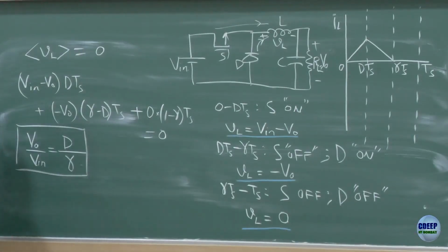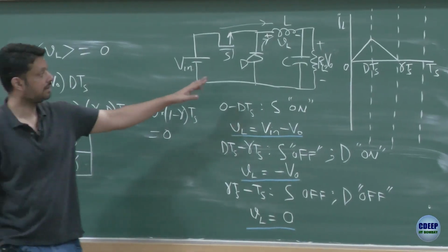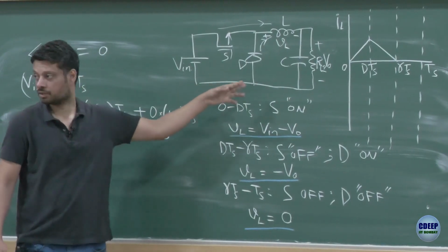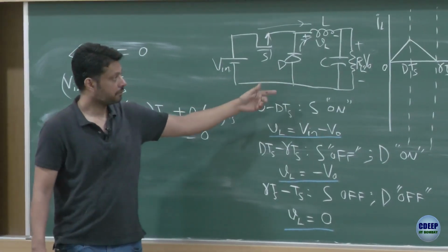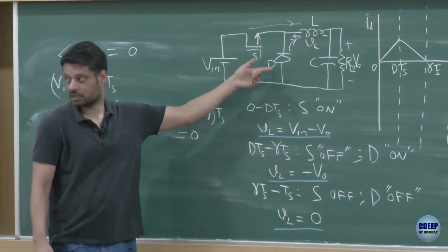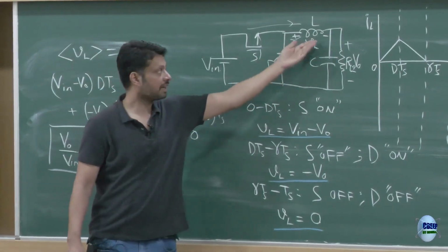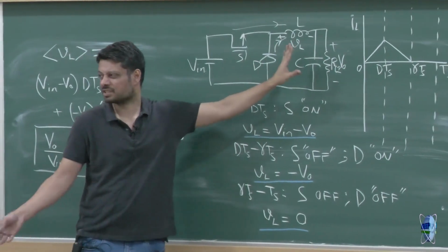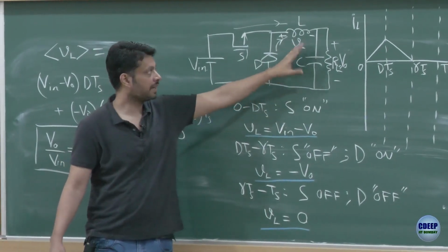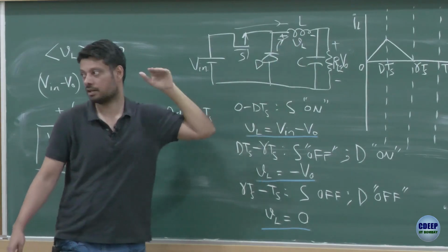Okay, so you asked me the question whether I can repeat the part where the diode turns off, right? In the second period, the diode is on, right? So the equivalent circuit is just this one. You have an inductor, you have a voltage which is almost a stiff voltage source, which is applying minus VO. Inductor current is falling.